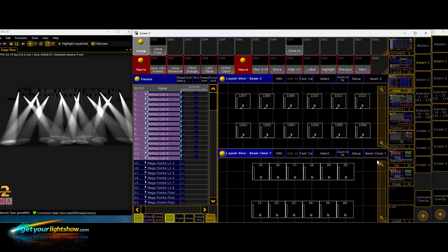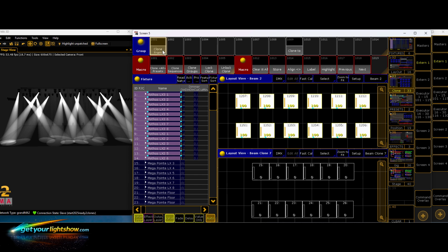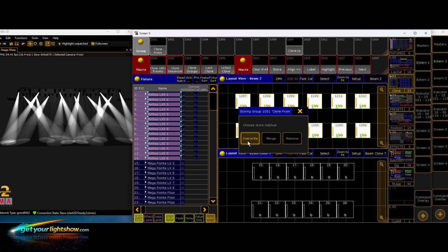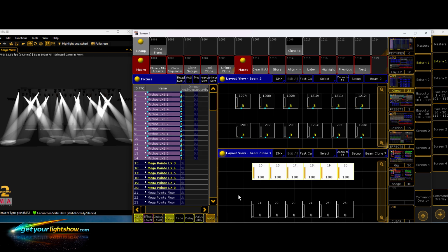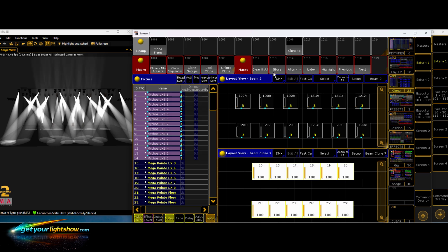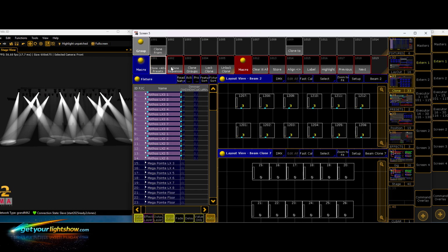Let's go to our beams. Here it's easy, it's 6, 6, 6, 6, so we can go simply from left to right, left to right. Store them here to our clone. Let's do override. And doing the same with our destination. Store here, override. Clear everything, and let's do the cloning.